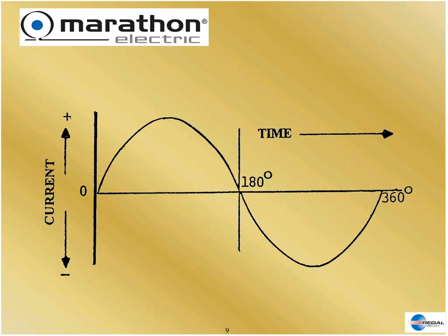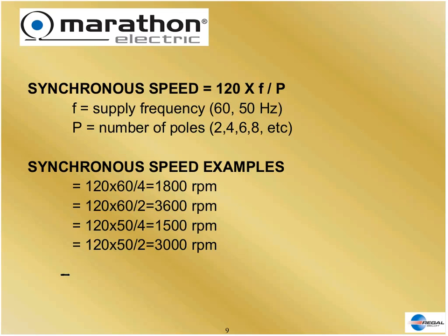This is a single-phase waveform. You notice whenever there's a peak, there's no valley at the same amount of time. And the wave, therefore, rises and falls, but it does not travel by itself. It rises and falls. In order to use single-phase power to make a motor, we have to physically move this wave off of its dead zero point. You see that at 0 degrees, 180 degrees, and 360 degrees, this waveform transitions and goes through 0 3 times. So every minute part of a second, the waveform is going through a 0 point, which cannot produce rotation.